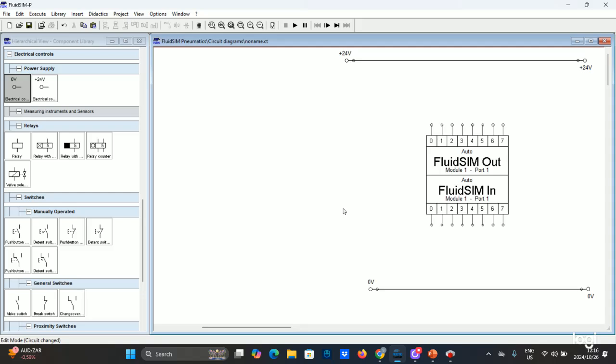And now, as I said, when you're designing your PLC, you always need to have, let's say, a start push button so that you can start the process. For a start push button, you want to use a push button that's not latched. We're going to latch the signal using our code. So this is our start push button. We connect it to power.